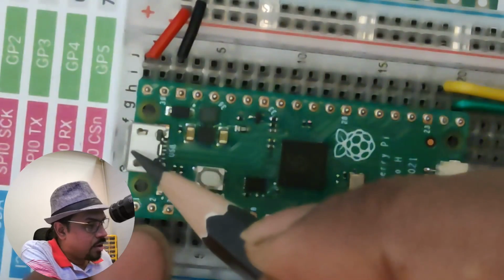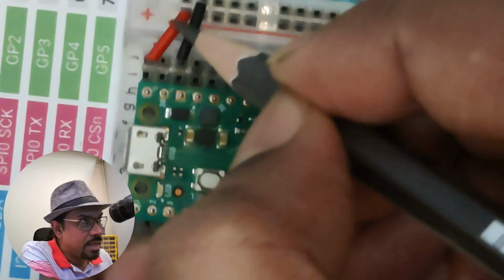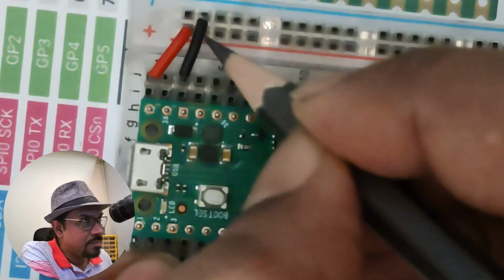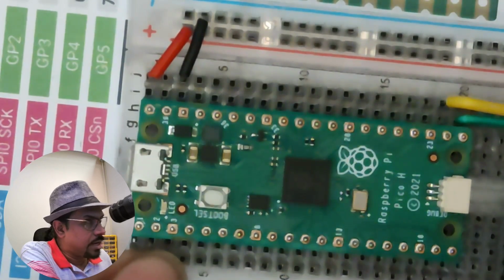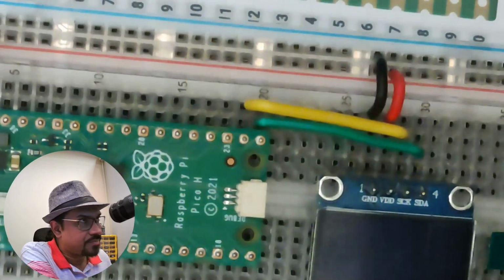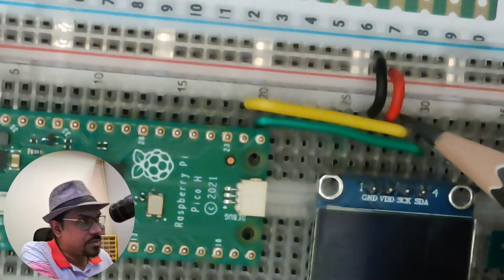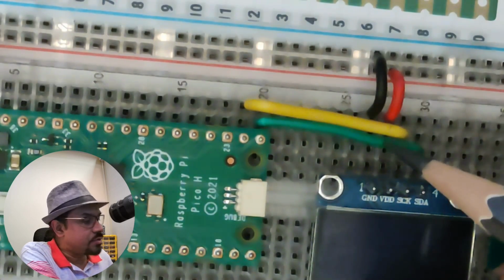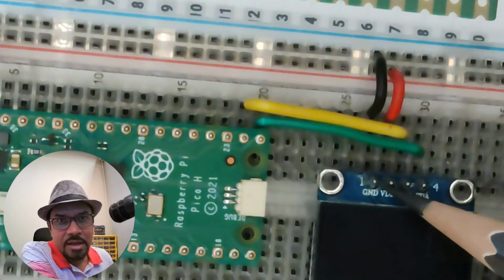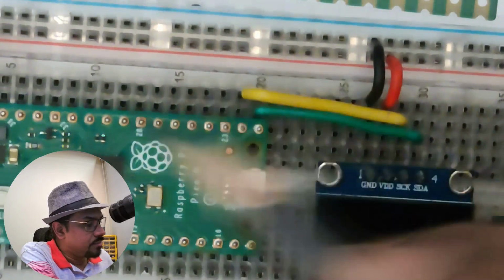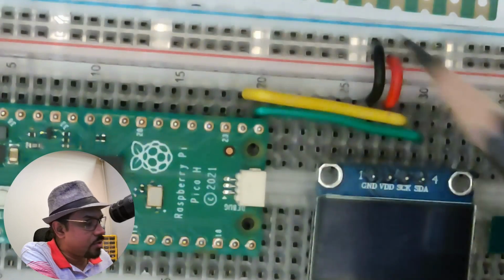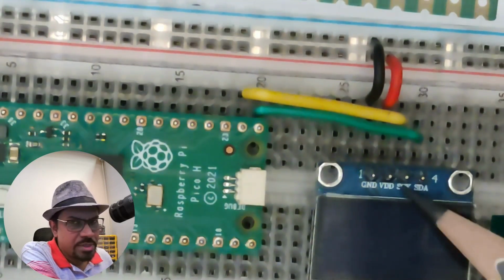So on this particular Raspberry Pi Pico, you can see pin 40 is connected to the positive lane right here. You can see the positive lane in this place. It runs across to connect to this side, with a positive lane on this side, which actually connects to the VDD, right? It connects to the VDD at this point here. So you can see ground to ground and pin number 40 of the Raspberry Pi Pico to VDD. And there are just 2 pins here.